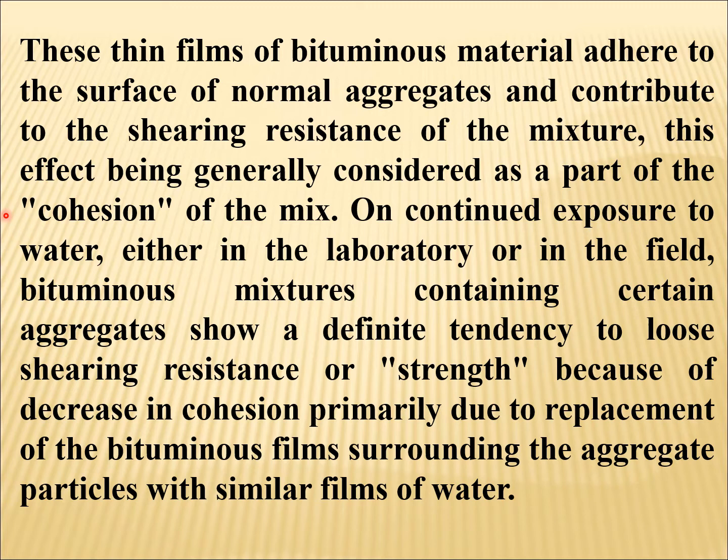So we use the term cohesion. On continued exposure to water, either in the laboratory or in the field, the bituminous mixtures containing certain aggregates show a definite tendency to lose shearing resistance or strength because of decrease in cohesion, primarily due to replacement of the bituminous films surrounding the aggregate particles with similar films of water.